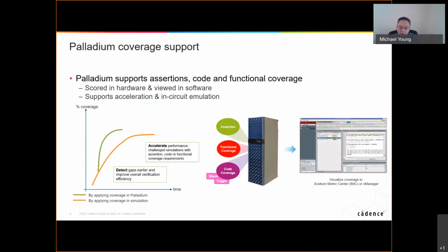But I also want to emphasize the methodology that has been in place in the simulation world for a long time, where they're tracking through assertions and functional coverage or code coverage, allowing themselves to track the progress of the design, how well it is behaving, and whether they are testing in the right area. The same methodology has been extended and put into emulation. The result is that you can now do more intelligent runs. You don't necessarily need to run 100,000 tests if half of them provide the same coverage. So you can be smart about this.